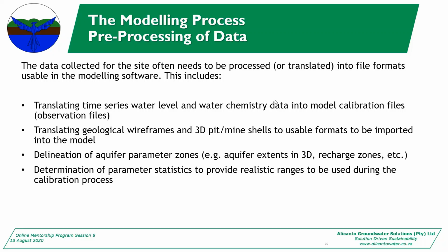Yes. Great. Okay, then you have to determine your preliminary model extents. How big is my model going to be? Is it going to be 50 kilometers by 50 kilometers or 500 meters by 500 meters? And then also your thickness. If I am mining to a depth of 100 meters, my model needs to be at least 100 meters thick. If I'm digging a hole down to 15 meters, it needs to be at least 15 meters thick.